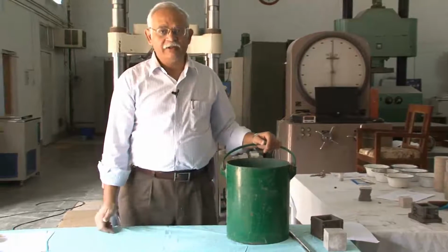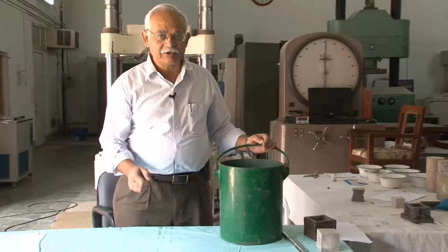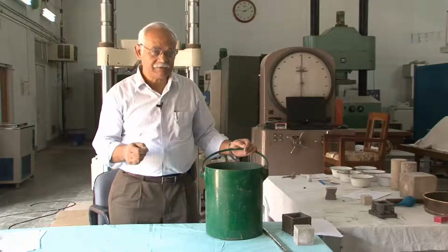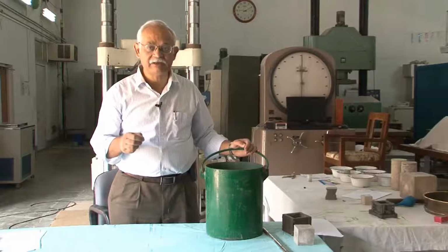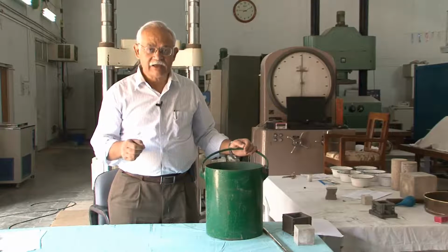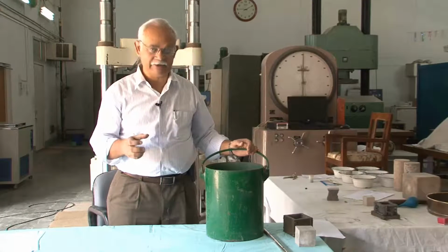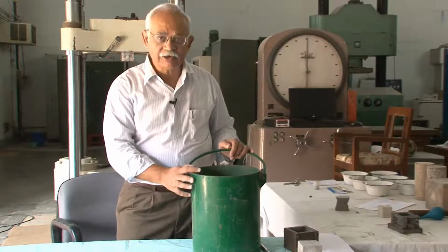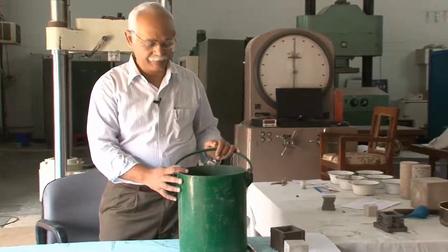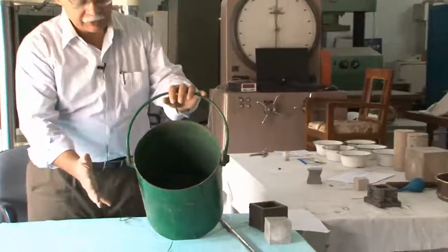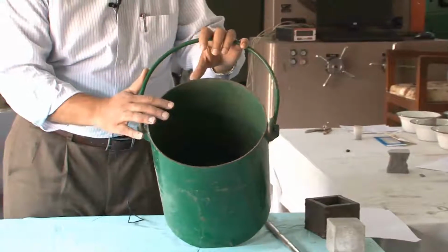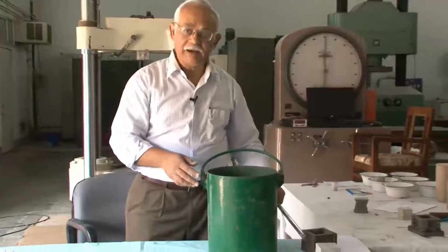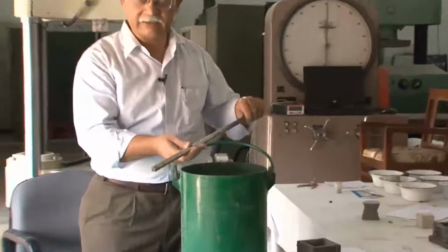We have been talking about the difference between the specific gravity of coarse aggregate or fine aggregate and the bulk density. The specific gravity is the density of the material per se. The bulk density includes the volume of voids which may be there in the aggregate when it is packed. Now, in order to determine the bulk density, which has its own use, we use a fixed volume container, something like this, fill it with aggregates in a certain manner, whether it is 3 layers or 4 layers or whatever, compacted using a tamping rod, which is something like this.